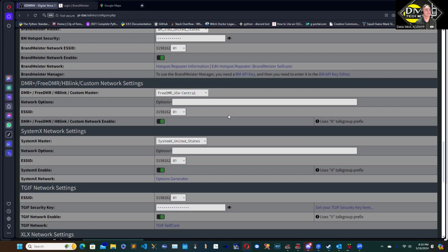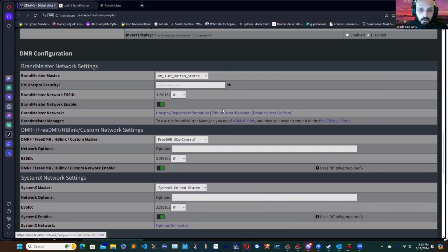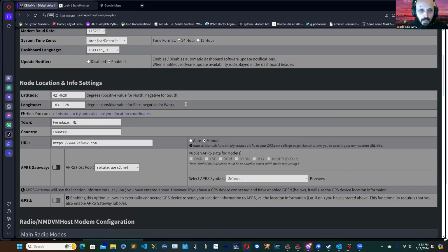Hey, Brad. Yeah, go back up to Brandmeister and where it has your Brandmeister Network ESSID, that's your digital ID. What's the drop down behind it? What is that? 0102? What does that do? Yes. If you have more than one hotspot, you want to put a number behind each one. That's so they don't interfere with each other.